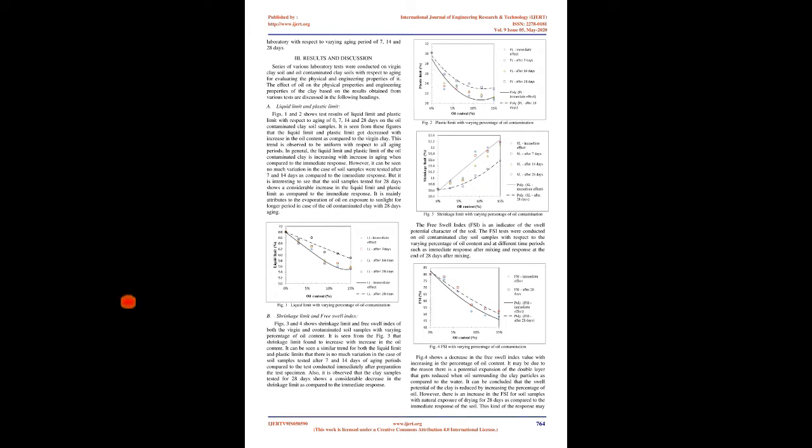The engine oil was added to the soil sample and mixed thoroughly in proportion to the weight of soil. The contaminated soil samples were exposed to natural weather conditions to study the effect of aging. The contaminated clay soil samples were tested in the laboratory with respect to varying aging periods of 7, 14, and 28 days.